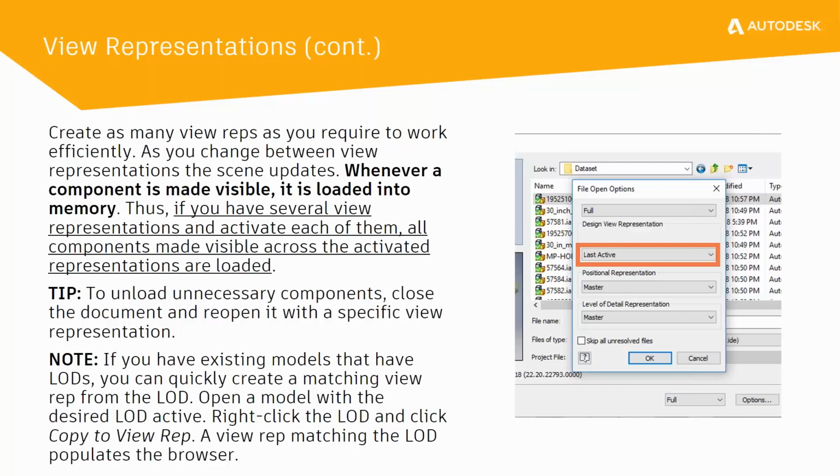The good thing is you can create as many of them as you like, so you're not limited in the number you can create. But remember that whenever a component is made visible, it's loaded into memory. So if you've got numerous view reps and you're switching between them, each time you switch, it's loading all of the components into memory, and they will stay in memory even if you switch to another view rep.